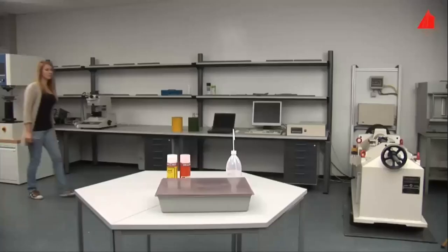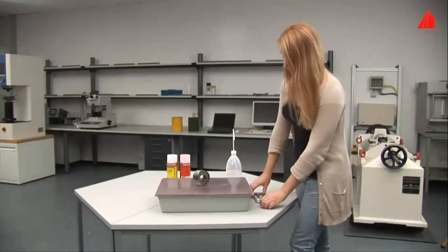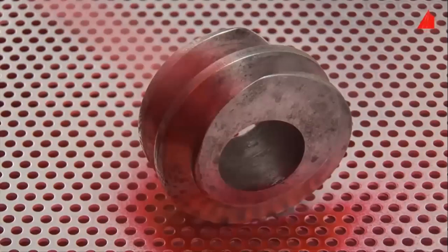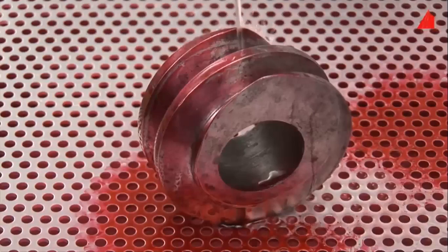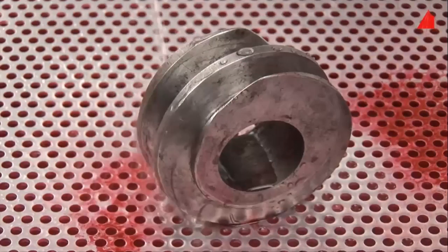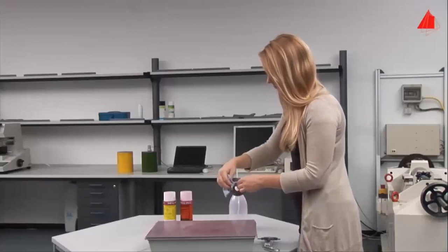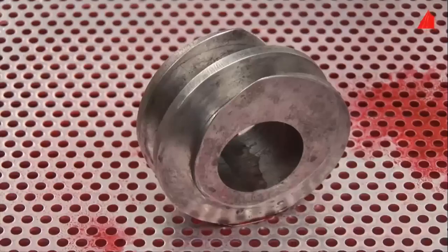We wish to inspect two samples, a segment of a worm gear shaft and a broken bicycle crank arm. Both test pieces have already been cleaned. First in line is the worm gear shaft. The material tester applies the penetrant. After a dwell time of about 10 minutes, she removes the excess penetrant from the surface by rinsing the test piece gently with water. She takes care not to rinse for an unnecessarily long time because the penetrant is supposed to stay in the defects. Now she dries the surface of the sample with a cloth to absorb the excess water. As the final step, she applies the developer and lets it dry.